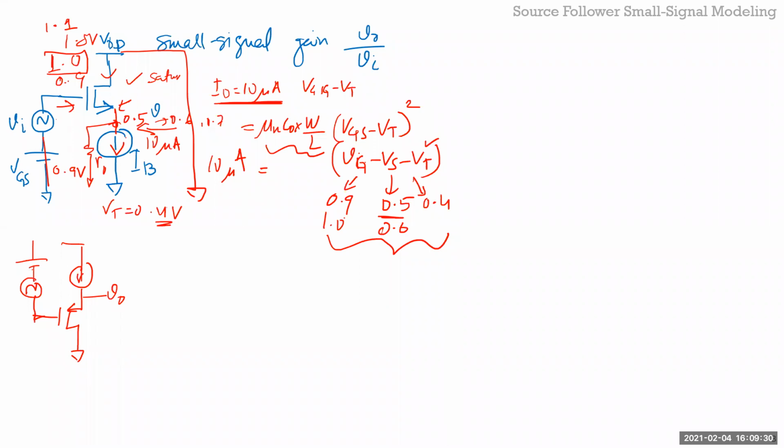And same procedure, right? Take the 4-terminal device, the transistor, plug the small signal model into it, and solve using your linear network equations, the 3-step procedure we follow. Choose your ground, choose your nodes. There will be an independent source in small signal as well, which is VI, or I, whatever it is. And then write the KCL equations and solve it, right?